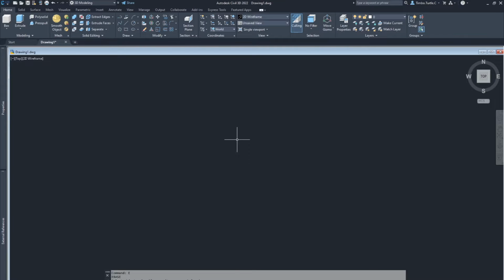As I said, AutoCAD is really, in this element, just a drafting program. It just draws whatever you tell it to. It's pretty much garbage in, garbage out. But let's try not to put garbage in, let's actually put something sensible in. So, as I said, first command, let's draw a circle. Now, as we're going to test the idea of the shape of the Earth, or the curve of the Earth, let's draw a circle that is actually the size of the Earth in miles. So what I've just done there is put in the circle. The first thing it asks me down the bottom here is where the center of the circle is. So for the start of it, I'm just going to assume the circle is at 0,0.